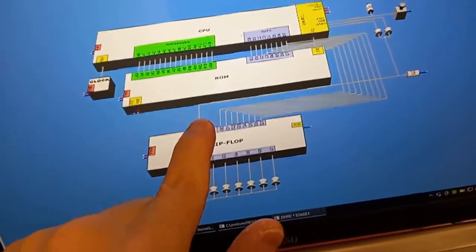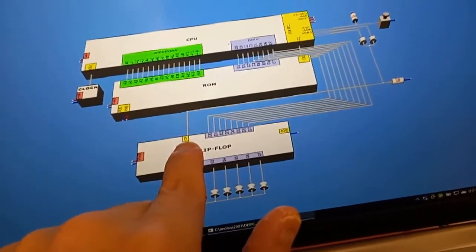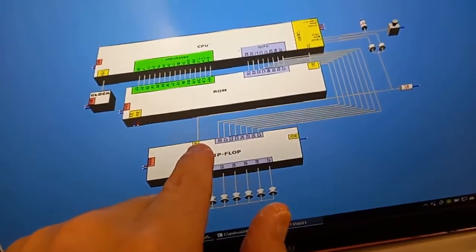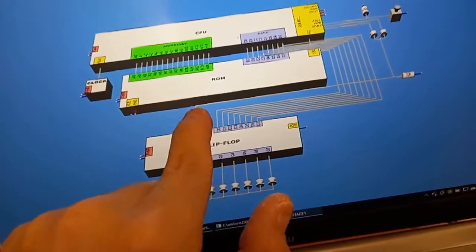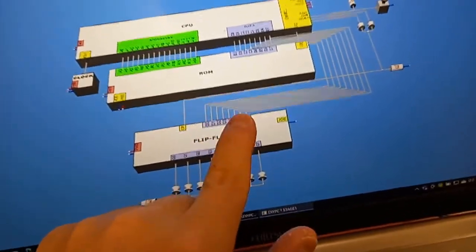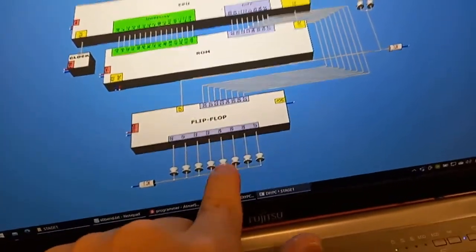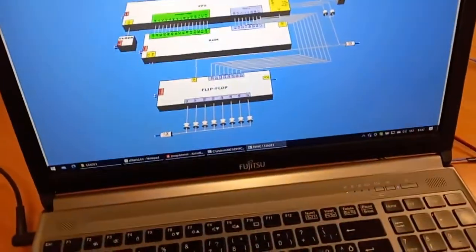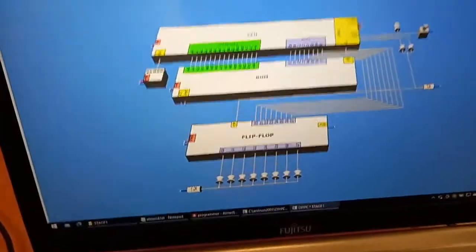And then the CPU has finished outputting. It's releasing this capture button, and then it's getting high, and then whatever changes on the data bus is not going to be reflected here. So we have CC sitting here just like this. But you can see it all in video number 1 and number 2, how this works.